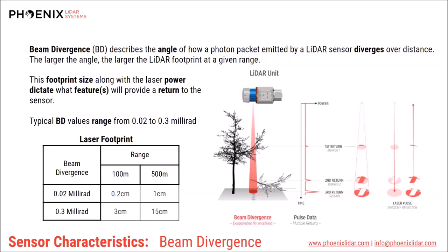Like if you were scanning over the green of a golf course where points would be 2 centimeters apart, then there's sensors that can see those 2 returns and discriminate them, and maybe place points at the bottom or top of the grass, and others that would just say, well, that's a rather wide return, but it's 1 return. And it really depends on the signal processing in the LiDAR to determine that minimum distance between 2 returns of a single shot.